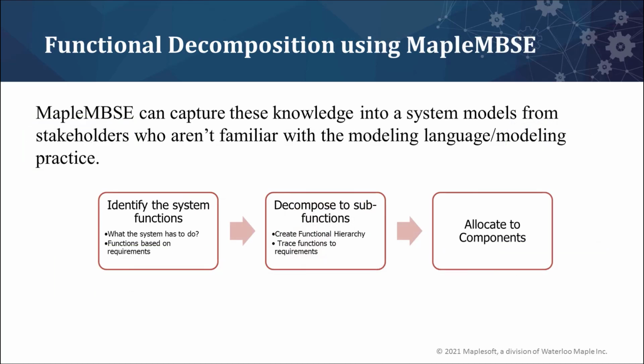So the way MapleMBSE can help with functional decomposition is we will identify the system functions. The user can define what the system has to do based on the requirement. We will decompose a function that we identified into sub-functions. We will trace or link the function to a requirement, and we will allocate the functions that we break down to the components that are going to perform those functions.